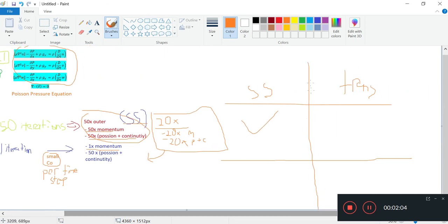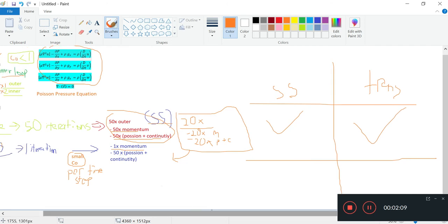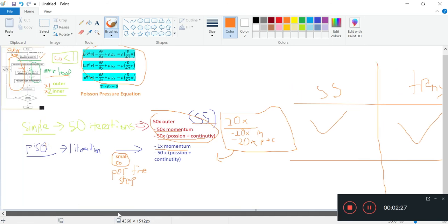Now, of course, you can apply the same strategy to transient simulations. So per time step, you will keep solving the outer loop until you get convergence. So per time step, you solve the outer loop again and again until you get convergence. However, this methodology is pretty slow,